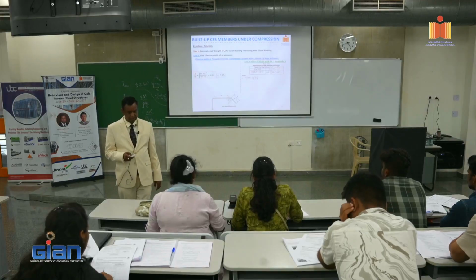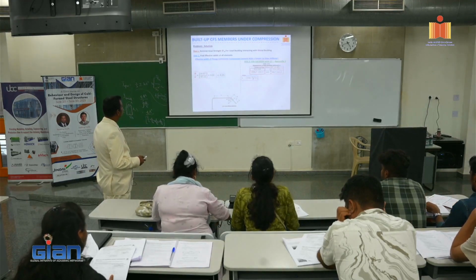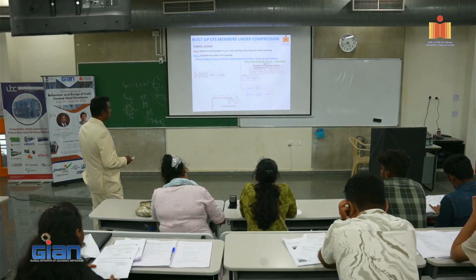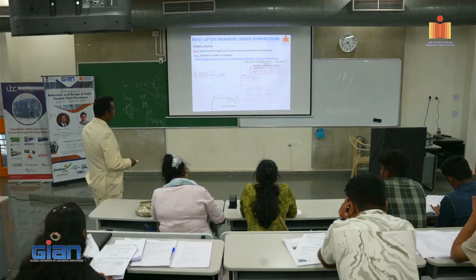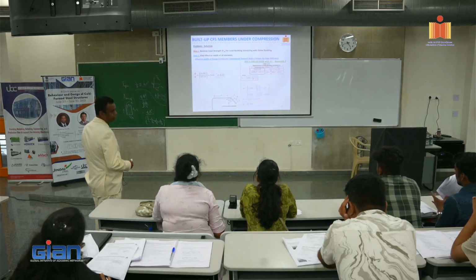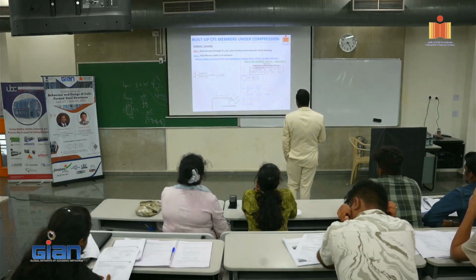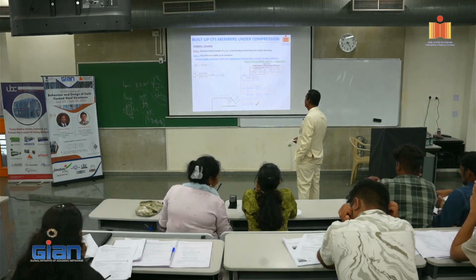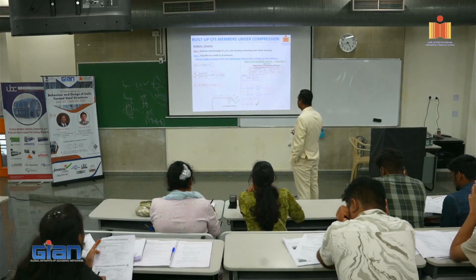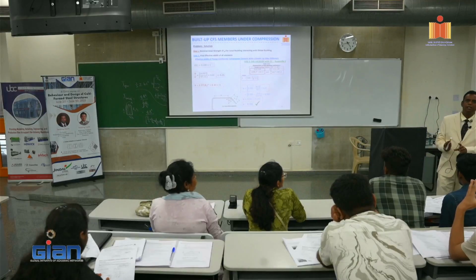k equals 3.57 Ri^n plus 0.43. To use this equation, I have to calculate n. n equals 0.582 minus W/t / 4S, and it should be greater than or equal to 1/3. So this becomes 0.342, it is greater than 0.33, which is what it has to be. So we got n equal to 0.342. Now we already know Ri, which is 0.149. So when we put it, k equals 3.57 Ri^n plus 0.43 and should be less than 4. What is the meaning of this equation? This equation is telling you something.